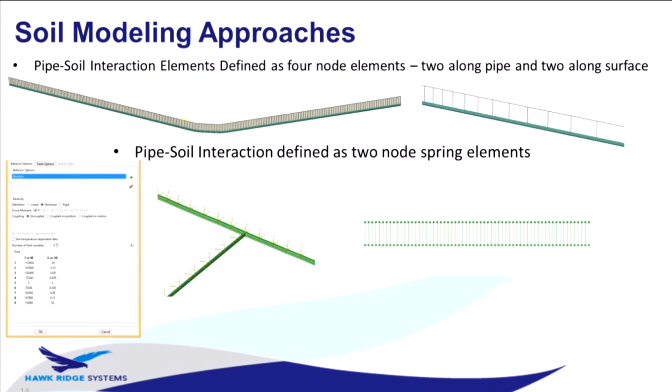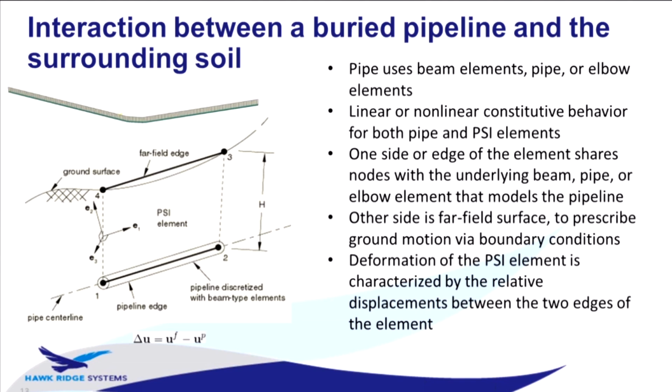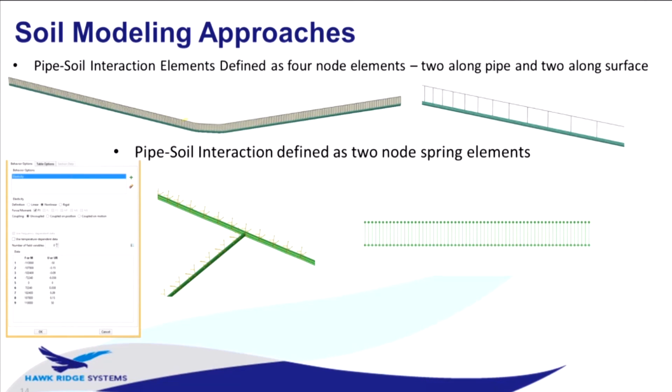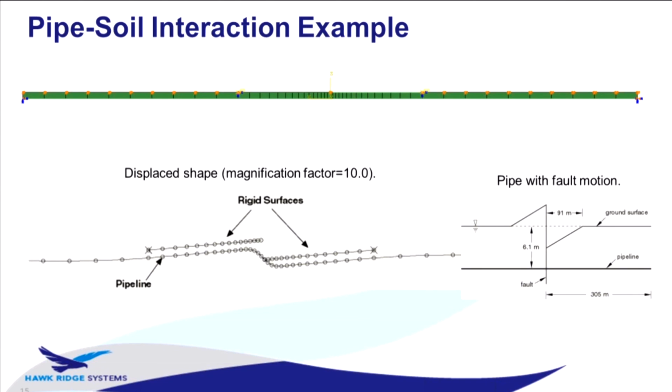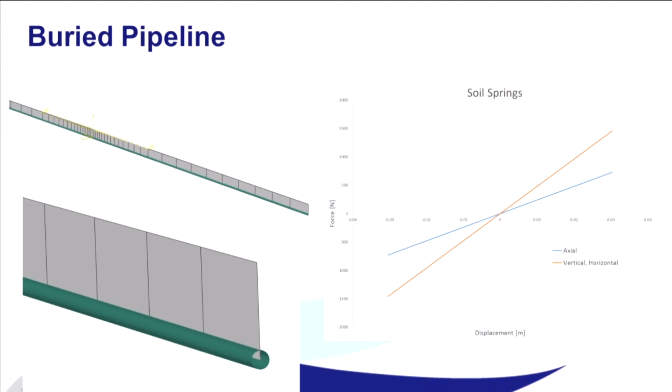With the pipe element, that's a really common study that people in pipeline and structural analysis do, where you're looking to embed that pipe in the soil and see how it reacts to some sort of soil movement, whether that's an earthquake or some other soil movement. And the unique thing about that one is that we're able to create really detailed models of the soil property along the length of the pipeline, from information like geological surveys. So really rich, deep information to dig into.